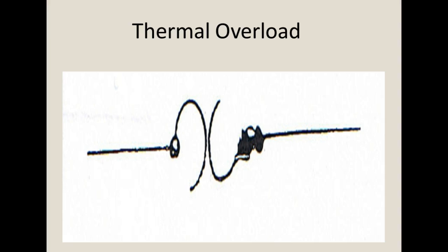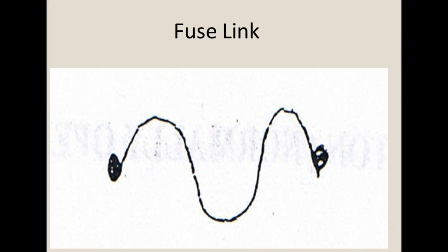In the older days, where this wire comes into the porcelain, we would put a fusible link, right? That's what we're on right now, fusible link. Now you go like, well, I've heard of a fuse. And y'all, this symbol is the one that gets missed. There's two of them, a fuse and a fusible link. Most people miss that on the test. Two humps up, one hump down, right?